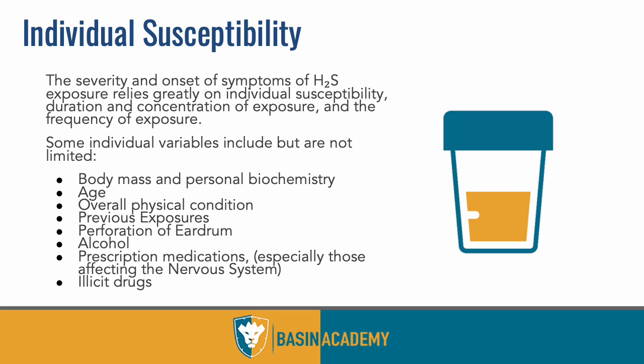So just a little fact out there, 10 parts per million is the industry permissible exposure limit, meaning you can be around 10 parts per million for 8 hours a day. But they've done studies about people who've been around 10 parts per million for 8 hours a day for 30 years, let's say, right? And these are people that work in the smelting, typically ore, some sort of mining or metal processing, right? Guys that have worked around that. They're within the range, but over 30 years, the statistics, as you can probably imagine, are not great. People get sick. People get really sick. A lot of different health issues.